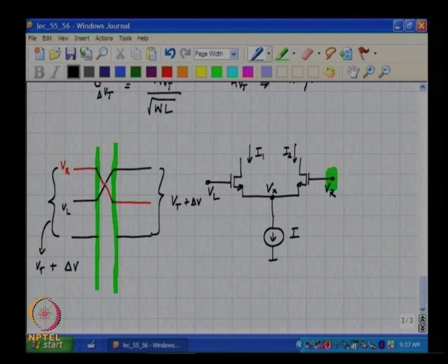What do you think will happen when we are at this point where the two drive waveforms cross each other? It will not be the average value, both of them are carrying the same current. So, the difference you have to worry about is how much lower than the average value of VL and VR the node Vx will go to.